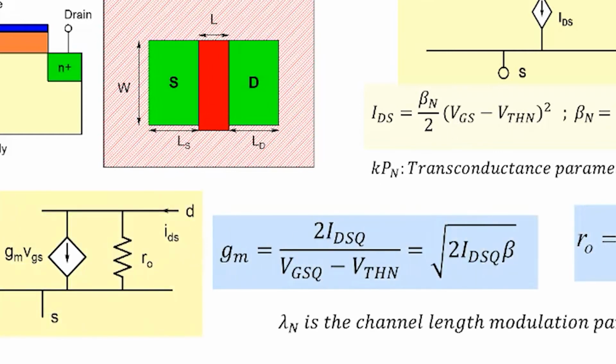The small signal model of the MOSFET, or the AC model of the MOSFET, is shown here. All AC or small signal quantities will be shown in small letters here, g small, s small. Between gate and source we have nothing, because there's an insulator. Between drain and source, we have a dependent current source, gm times vgs, and we also have a resistor ro, the output resistor. If you recall our discussion, we said that any three-terminal linear unilateral device could be represented in this particular form. In the more general case there was a resistor here, but in this case, the resistor value is infinite.